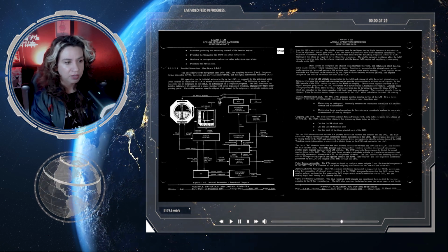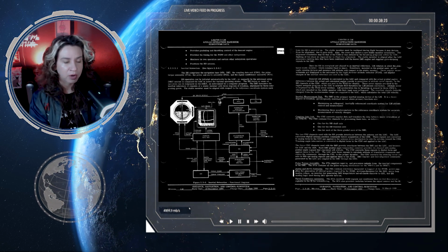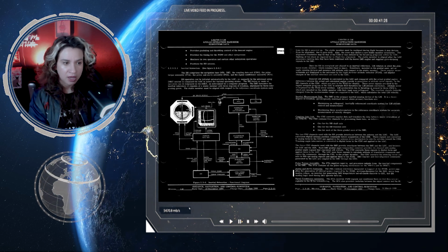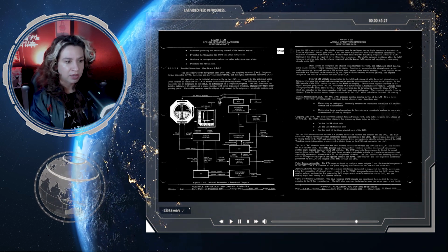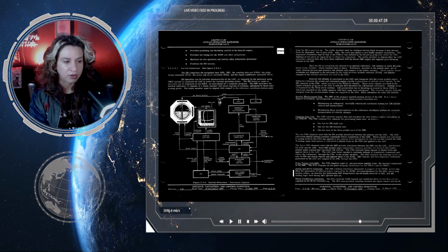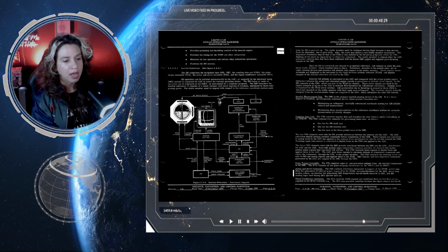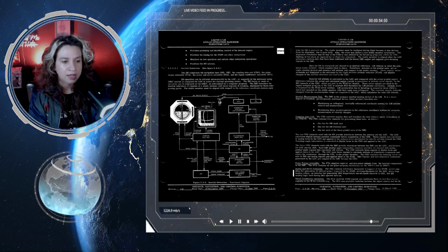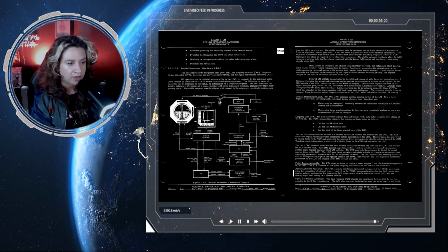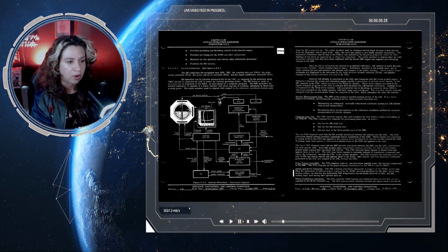Power supplies for generating internal power required by the PGNS. Servo mechanisms for the IMU, servo loop monitoring relays, and circuits for generating the IMU temperature out of limits discrete to the GSE. The ISS monitoring logic is used during the IMU operate turn on.